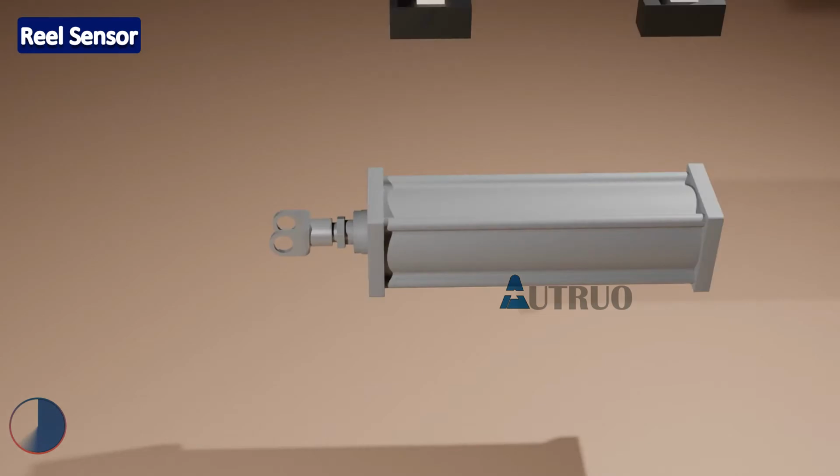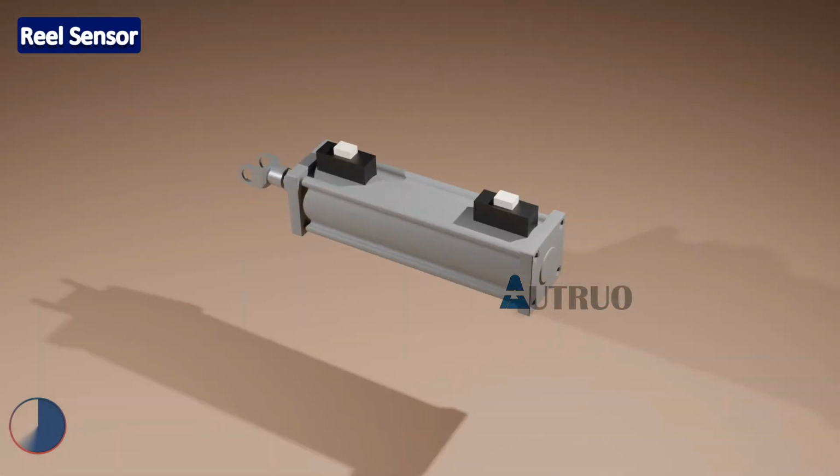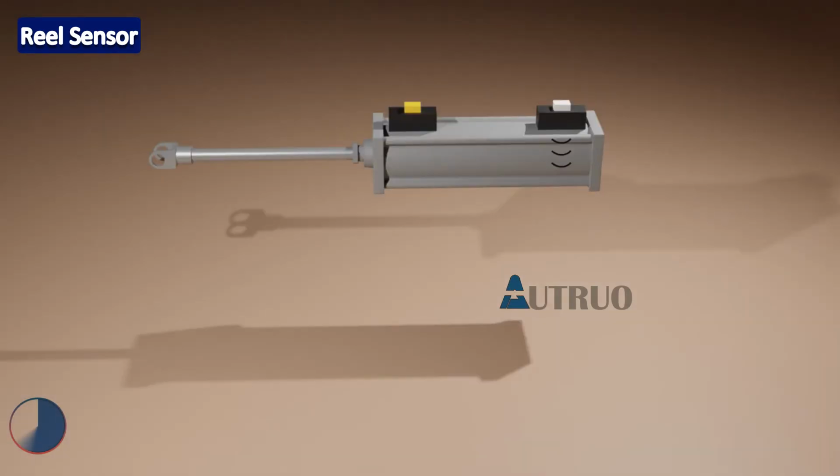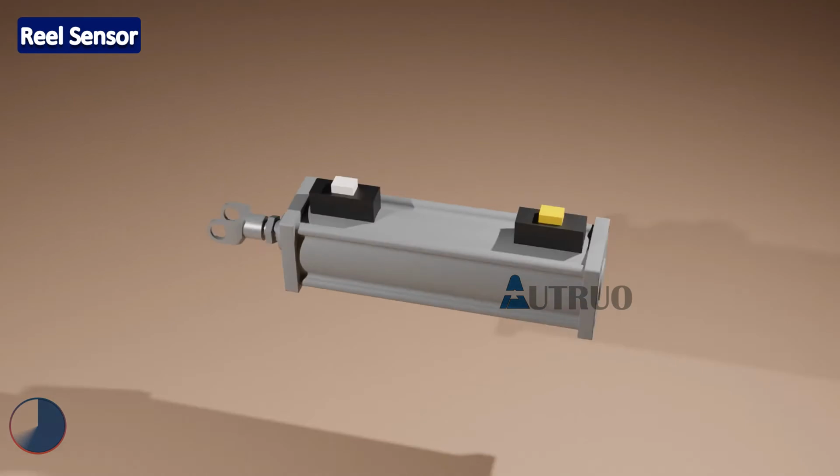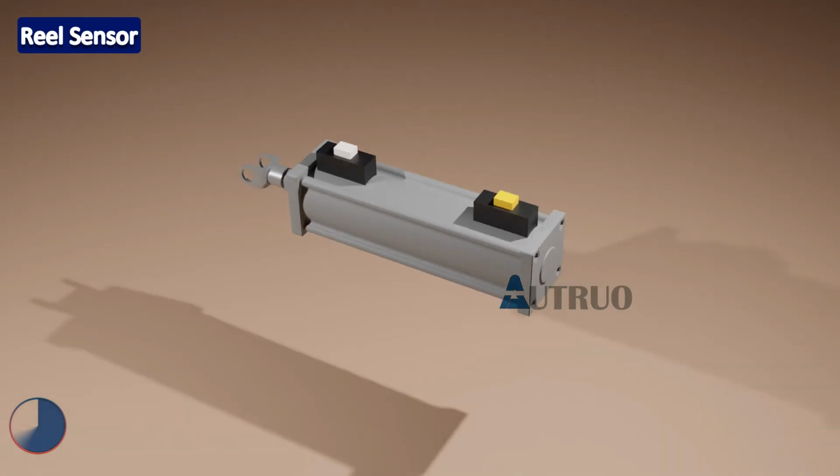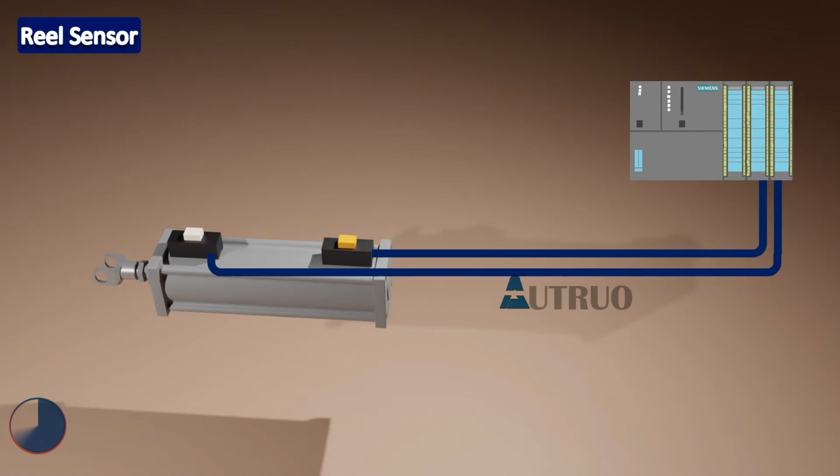It is usually mounted on the surface of the tracking medium. The magnetic field induced by the sensor will be affected by the tracked object as it moves towards the sensor. The generated field will react with the metal object, and the sensor will switch and send a feedback of 24 volts to the logic controller.